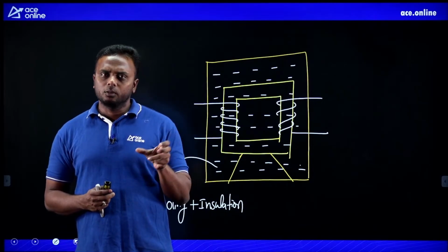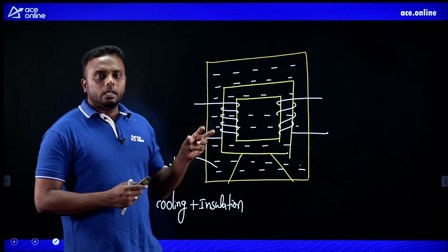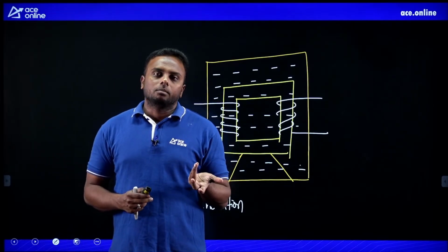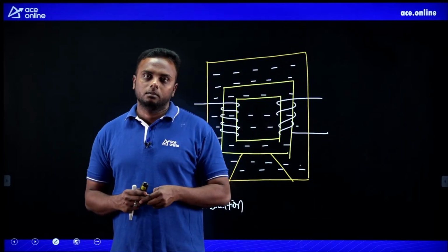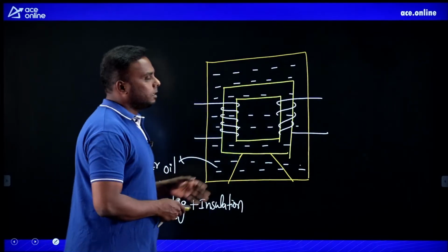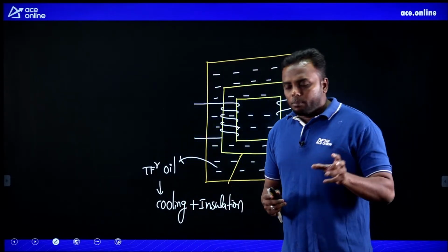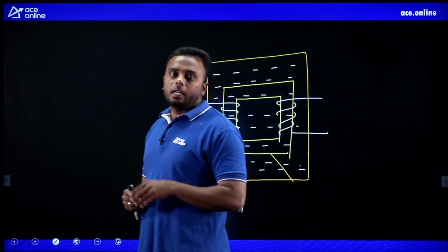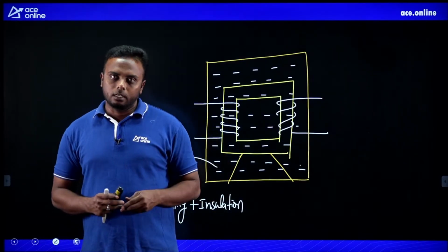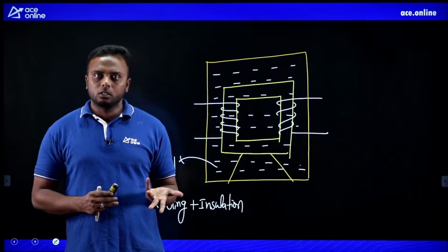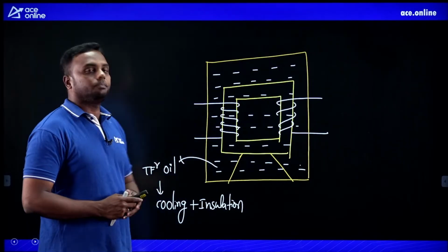These questions are also important, as we had in some previous RRB JE examinations, like when voltage is 2% higher, how much iron loss will there be with respect to rated iron loss? This type of question. Iron loss variation is approximately the square of the supply voltage. And copper loss varies with current. What variation? Copper loss is proportional to the square of the current. Iron loss is approximately the square of the supply voltage.